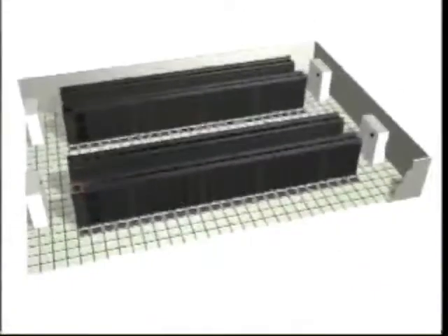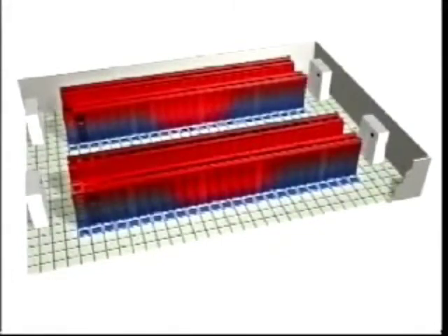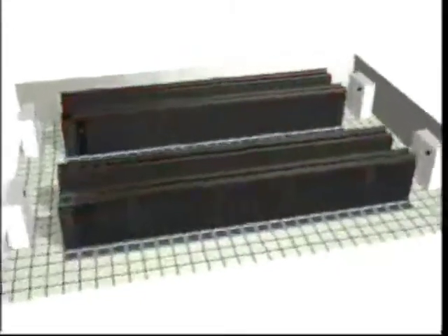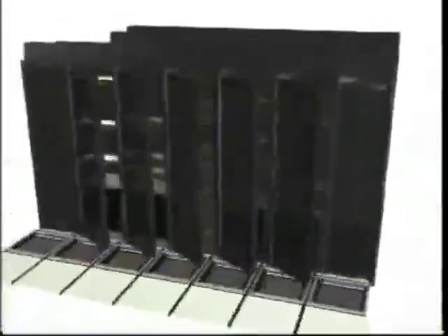Newer, more dense, and more compact equipment is installed. Each device generates nearly the same heat as the old equipment. However, the racks now hold more equipment, so the overall amount of heat produced increases. This creates localized hotspots around the data center. This also changes the airflow of the room by stealing air from neighboring racks with lower densities. To counter this, the data center manager redistributes the newer, denser equipment across several racks.